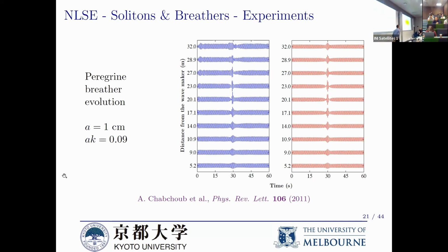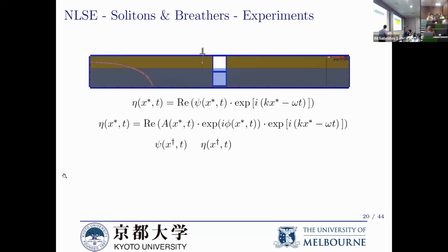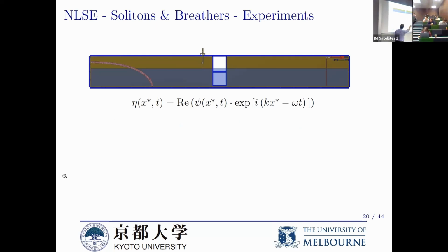But the free surface reconstruction has more terms, right? Oh, yes, this is a good point. Indeed. So we just define the boundary condition to first order of approximation. But of course, if you measure, you see the second Stokes wave, third, fourth, etc. You see the whole cascade. But these appear naturally afterwards, so I don't have to deal with it. If I generate a linear signal, it generates only nonlinear waves shortly after the wavemaker, so I don't have to deal with nonlinearities. And of course, I could be more rigorous here, adding the second Stokes wave, third, fourth, etc. We can do that, but it does not change much in this curve. Of course, yeah, thank you.